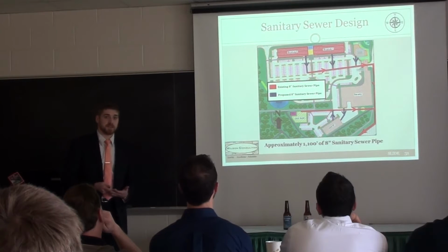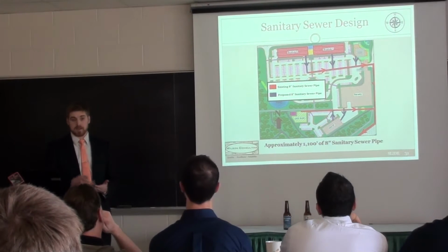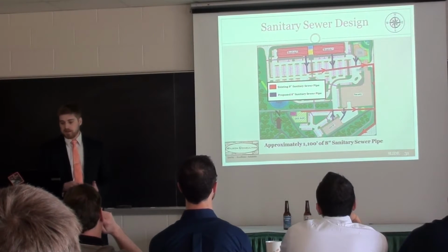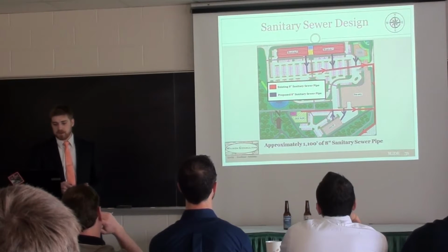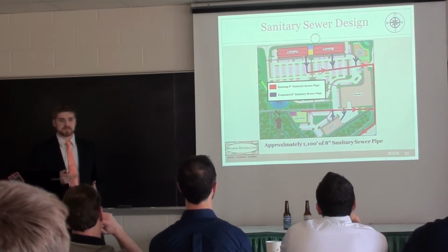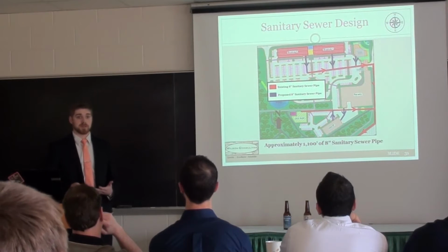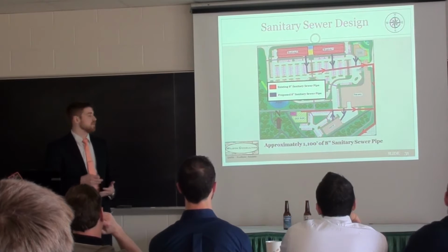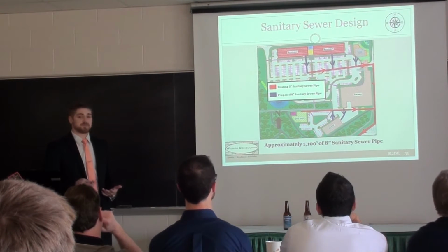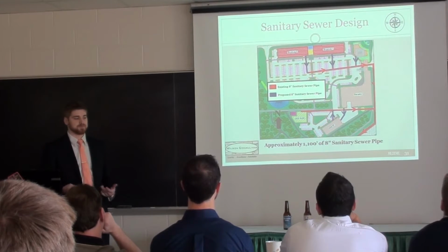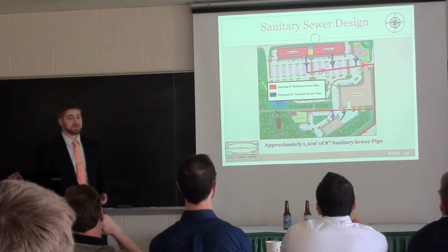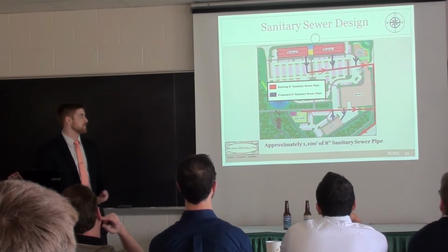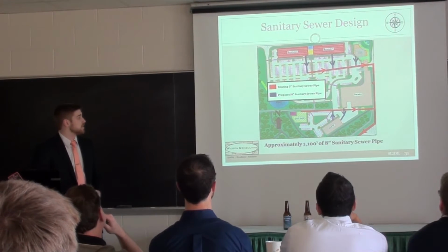And there were a few design constraints we had. It's a gravity-fed system. We decided to go with the 8-inch pipe because most sources we were looking at recommended the 8-inch pipe. There is a 6-inch minimum, but to account for possible further growth, we decided to go with the 8 because replacing these pipes to accommodate a higher flow of wastewater would be very costly, having to excavate much of the parking lot.